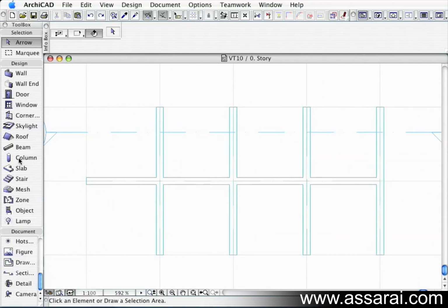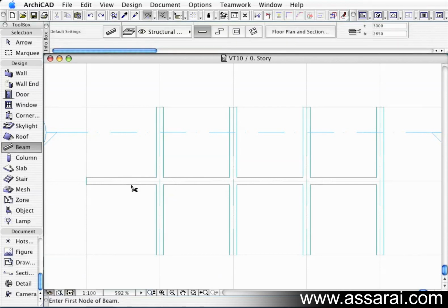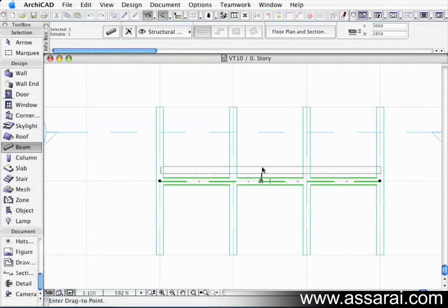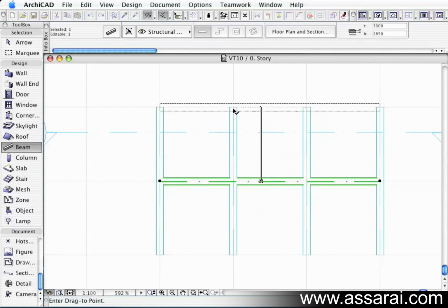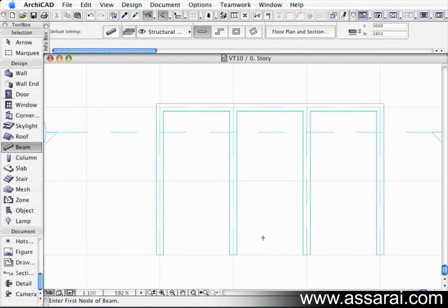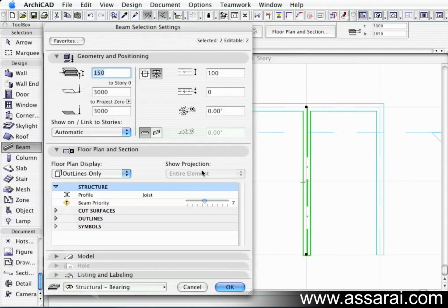So I might just click on the beam tool, trim that back by holding down the Apple key or Control key, and then move this by going Apple D, left mouse clicking on it, moving it to the end there. And then I'm going to put these beams on slight inclines, so might make them 15 degrees.